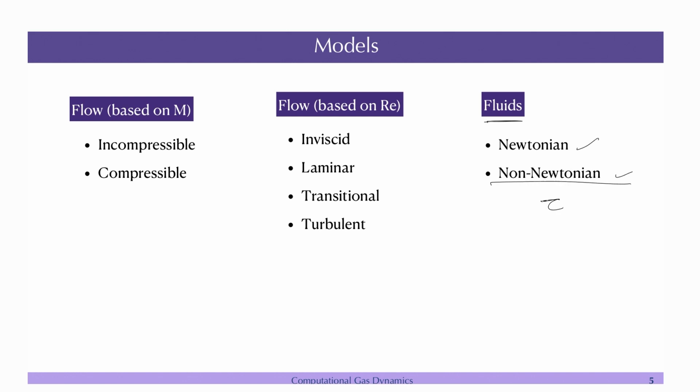So the tau that you have, in the Newtonian case we say that tau equals mu du by dy, if you have a 1D flow like this. Similarly we have discussed the constitutive relation. Depending on what fluid model you are using, the tau will change. Remember the conservation laws that we have, the mass, momentum, energy conservation, they will stay.